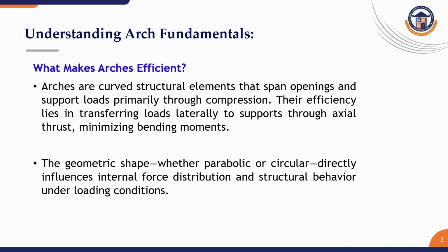Understanding the fundamentals of arch. What makes the arch effective? An arch is a curved structural member that transfers the loads primarily as axial compression to the supports. Instead of resisting loads by bending, arches push the load sideways to the supports. This lateral force is called the horizontal thrust. The shape of the arch plays a critical role in determining the internal forces.